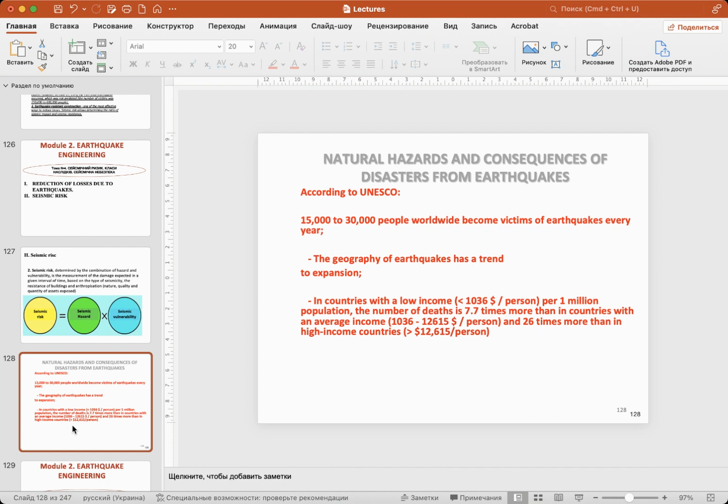That is why they are using bad structural materials. They are trying to economize in every construction and in every structural element, which gives a reduction of the amount of cement, and they are building poor cement concrete elements, which don't have the necessary amount of load-bearing capacity. Also, they're using cheap reinforcement. In some cases, they're trying to put less reinforcement than was shown in the design.